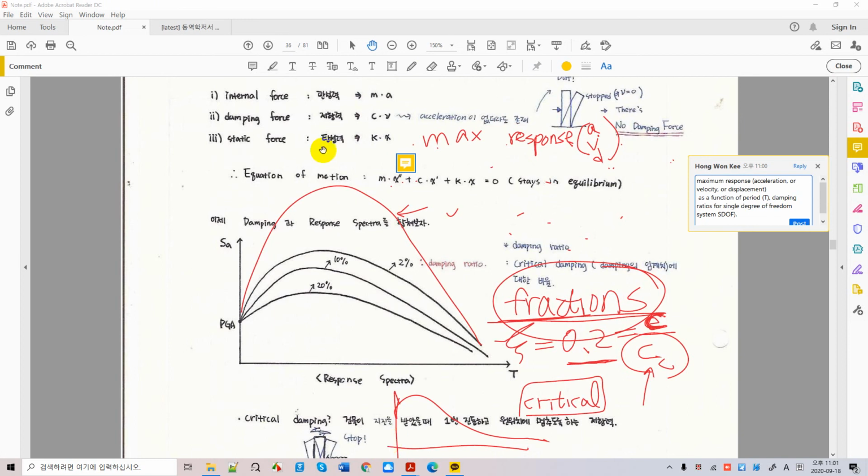It's very important. Okay, now let's make a conclusion on response spectrum analysis, right? The response spectrum analysis and definition. Okay, now we understand how to make a response spectrum analysis based on period on the x-axis, and for different damping ratios. Okay, the damping ratio is what again? Damping ratio is the quantity that makes your building slow down. It dissipates energy. It uses energy through heat energy and sound energy and all the energy, right? It just goes and stops your building.